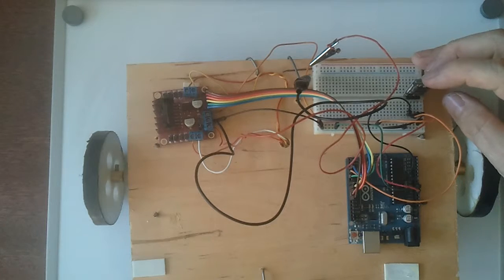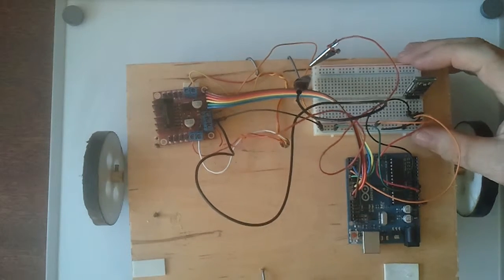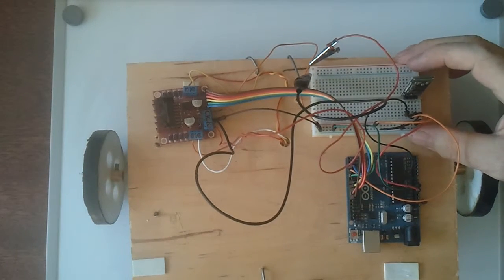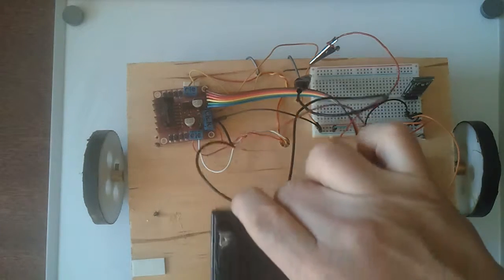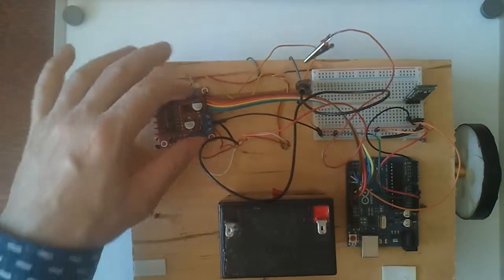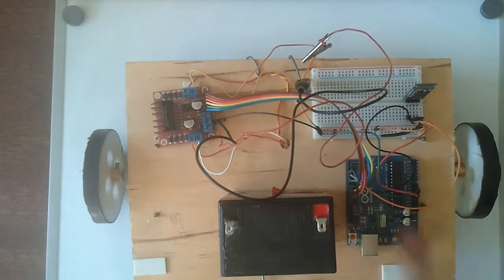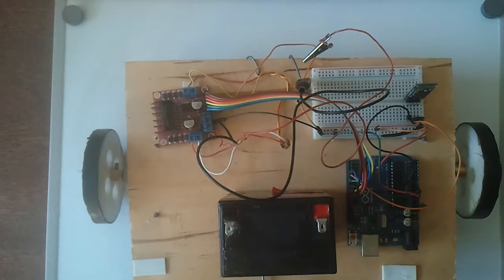They look like a serial line from the Arduino's viewpoint, and they communicate with the phone in that same way. So there's a cart, and it's driven by a lead acid battery, which is regulated actually through the motor controller, so that gives us a convenient 5 volts for the Arduino and for the Bluetooth device. So let's have a look at the code for that.